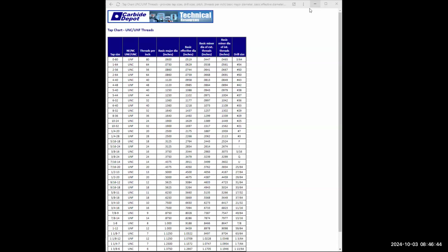We're going to do that again. Line. Click. Come all the way down. Click. Enter. Now, if yours is not snapping again to that edge, you have to type in OSNAP. You have to make sure you turn that on. That snap on is quadrant. Select OK. Otherwise, it's not going to snap to that quadrant. So line, see how it snaps to that quadrant? Come on down, click, enter. Now we have 2 circles we have to do it for.